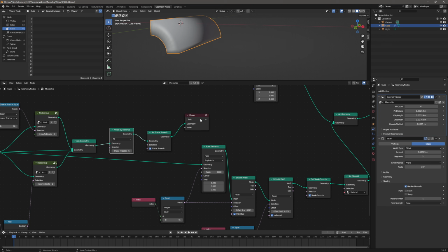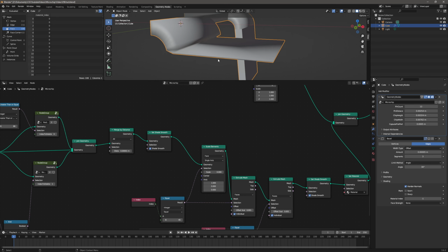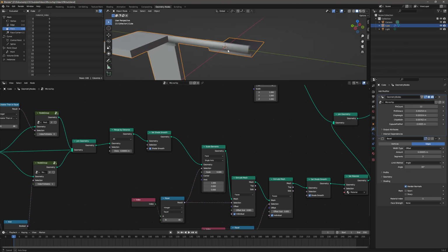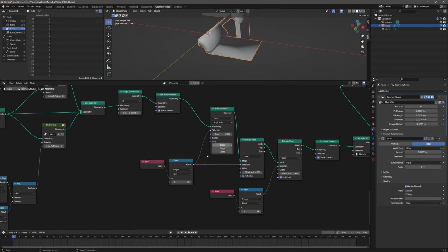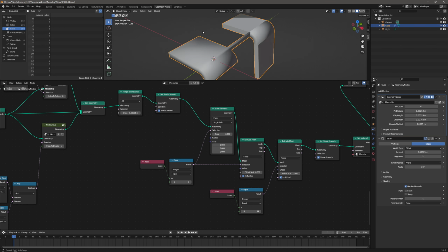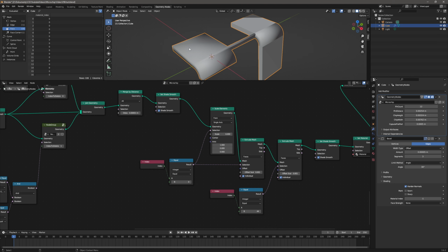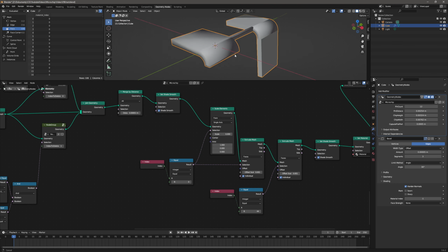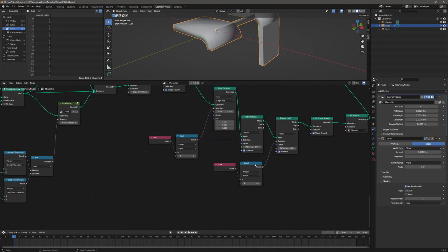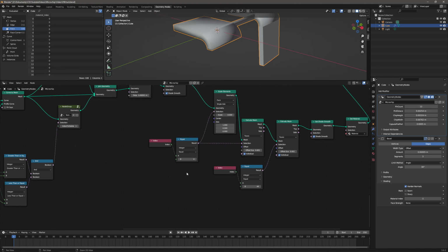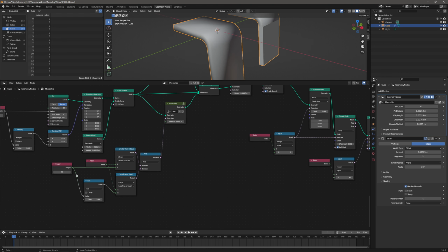So let's get rid of the viewer node and actually plug the geometry into the scales and the extrusions. Well, obviously the indexes have changed now, so we have to fix that. The first index is 0, actually. That is simple. And you can now already see with the bevel modifier disabled that the shading is becoming correct. The last index for the face to extrude is 45. It's actually the index of this edge plus 1.